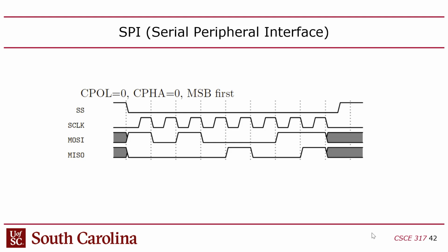Now this is the slave select being low for 8 clock cycles, and as I mentioned, it could have also been low for another 8 cycles, but the number of cycles should be a multiple of 8 because it's byte oriented. But the master was the part of it that decided that after 8 cycles were done. So this performed a 1 byte exchange. I sent a byte to the slave, and the slave sent a byte to the master, and done. Right?